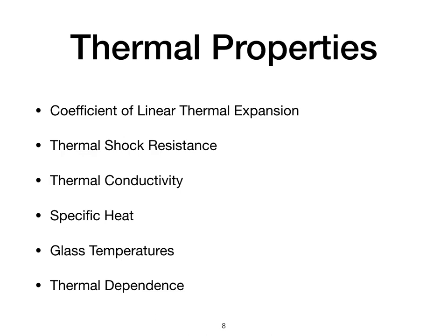It represents how well a glass conducts or transfers heat. So it is proportional to heat flow measured, cross-sectional area, and temperature gradient applied to the glass. Good thermal conductors will allow heat to travel through the material very quickly. It is often desirable for glasses to have low thermal conductivity in applications and act as thermal insulators. For instance, LEDs perform better in cooler temperatures and will output more light.